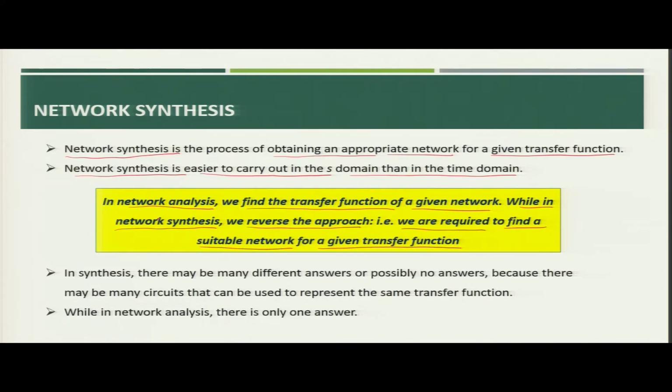So, in network synthesis, what will we do? We will get one transfer function, and from that we will try to find out the suitable network which satisfies the transfer function. Now, in network synthesis there may be many different answers, or possibly no answers, because there may be many circuits that can represent the same transfer function.